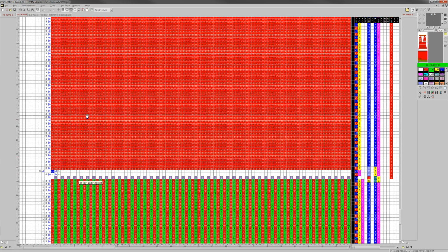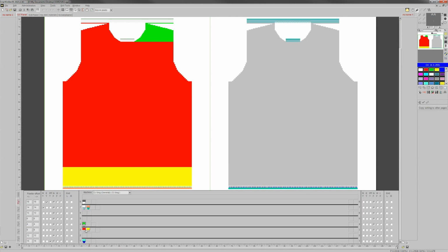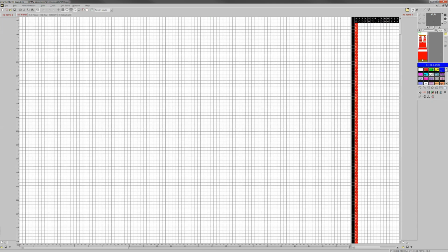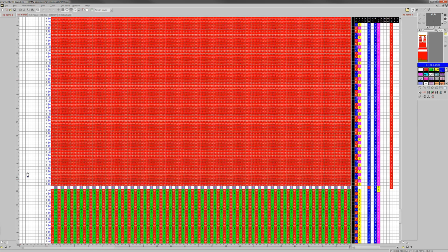After knitting the sweep, feeder 5 is brought to the right, and feeder 3 continues to knit the body of the panel. We could also use 2 feeders to knit at the same time, if the machine has 2 systems. When Knit with Duo Feeders is selected, an extra icon will appear. Drag to the appropriate feeder. The body is now knitted using feeder 3 and 5.